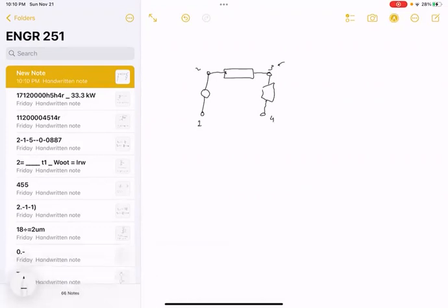So if we know the entropy at state 3, we also know the entropy at state 4. And of course, this is a cycle, so we have to have that sort of closure where we go from state 4 to 1, and we do this in a condenser. And it's in the condenser that we have our Q out, which is the wasted heat. We also have our Q into the boiler. And it's the turbine that's giving us the work output that we want.